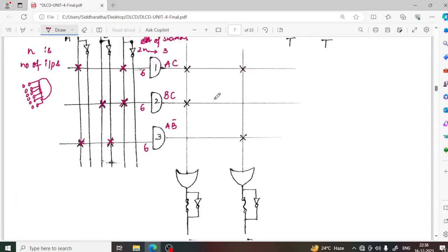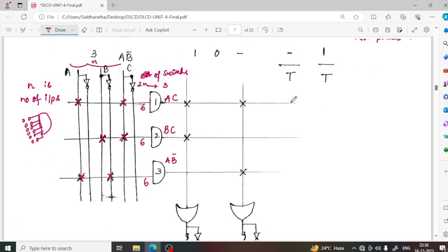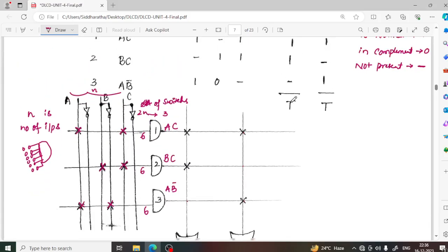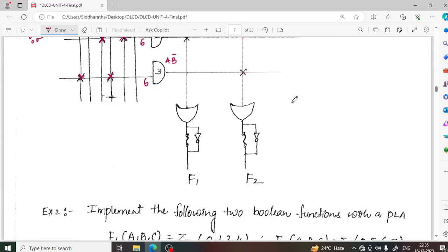Now, by observing the expression table, F1 and F2 may sometimes be taken in different forms instead of normal form, to get the distinct product terms. We may take the F1 bar to get the distinct product terms, but we require F1 to design. In such cases F1 bar is passed through a complement, then we can get F1. In such cases these NOT gates are helpful.